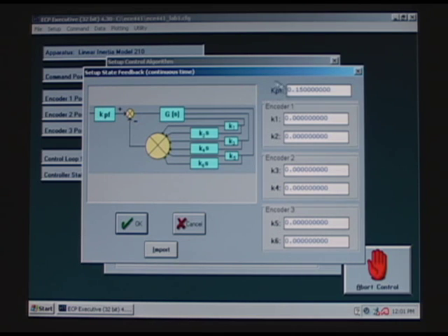Inside here you should see the K sub PF window, and all of the gains should actually be 0. The gains that we will be concerned with are K sub 1 and K2, which are the position gain and the velocity gain for mass number 1 associated with encoder 1 positional information. K sub PF, right now it's set nominally to be 0.15. That may or may not be a good value depending on what spring you are using. Right now I have it configured with spring number 4, and I believe I have 2 masses on the carriage.